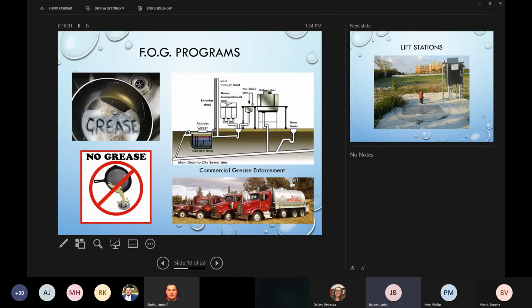One of the things that we see is you don't see a lot of typical home laterals clogging with grease. The homeowners don't have a problem. They don't perceive grease as a problem because it's not impacting their home plumbing systems. But we see it in the municipal system because of the temperature change that congeals the grease in the lift stations, combining and making its way all the way to the wastewater treatment facility.